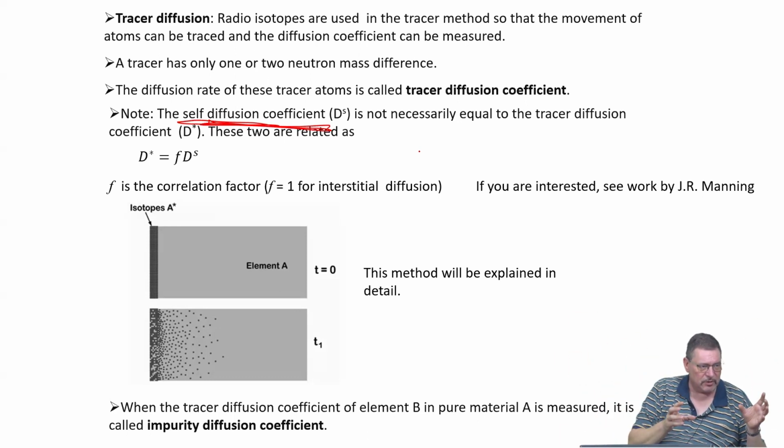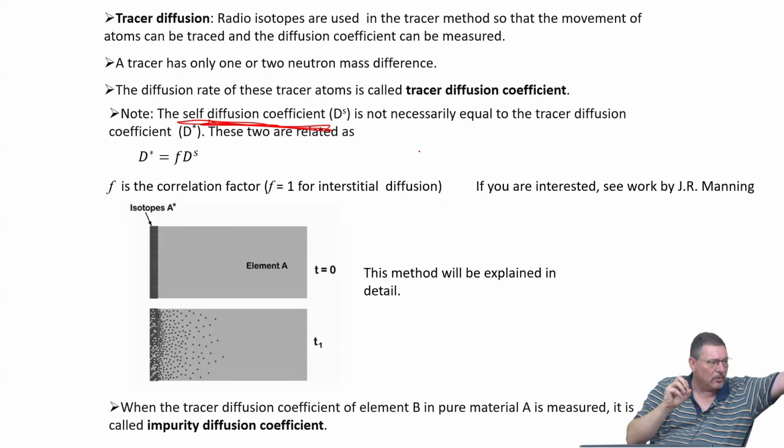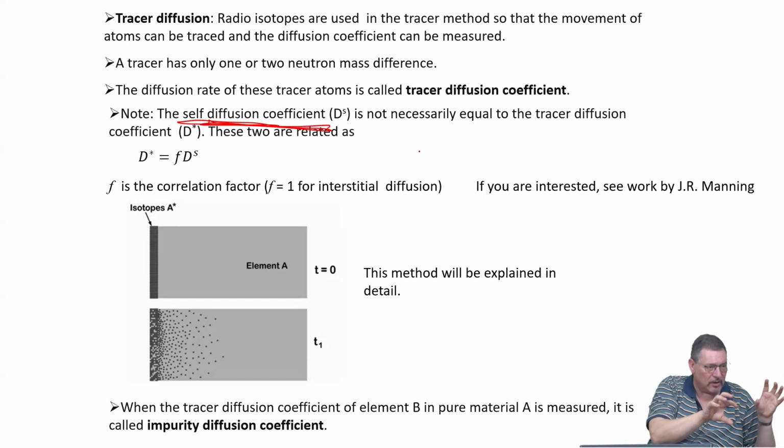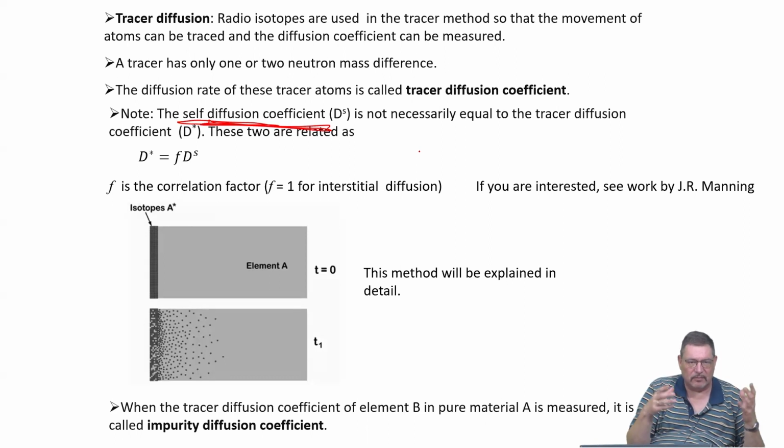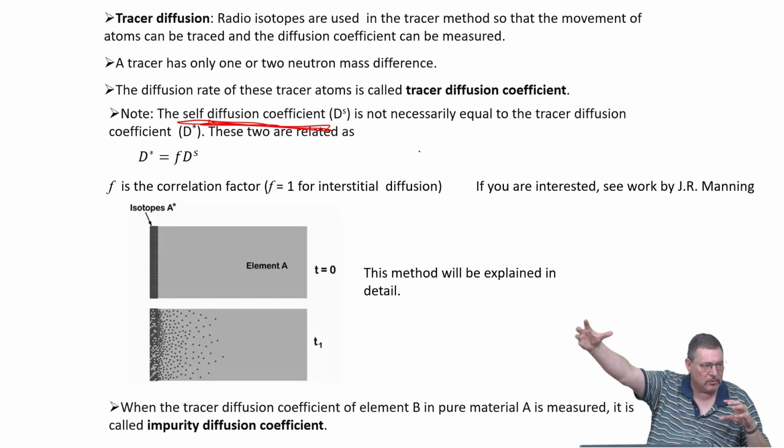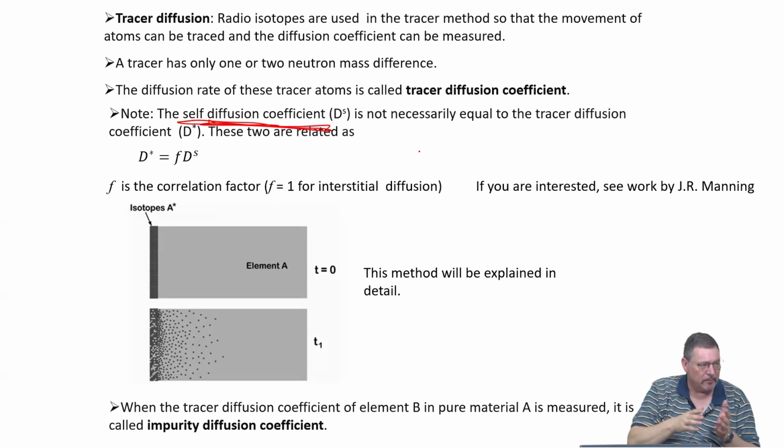If you have substitutional diffusion, there might be very different ways how the vacancy can interact on this lattice side or on this lattice side with the atom you are now observing. This is called a correlation, causing a correlation factor, causing cross terms in the diffusion matrix. So the correlation between random walk diffusion distance and real diffusion distance after n jumps for substitutional diffusion in real lattices will not be 1. And this difference, which is not 1, will be the so-called correlation factor.